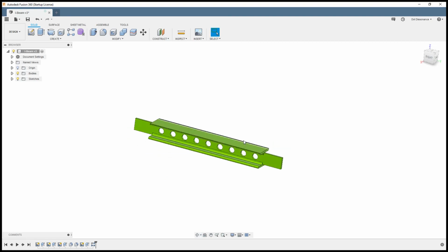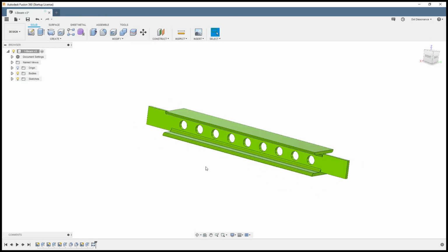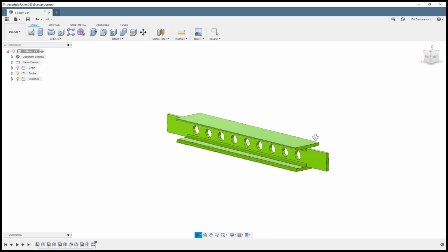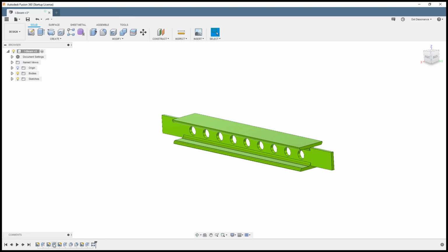Now, in this particular model, thinking ahead, and this is a really good design theory tip, I guess, is talk with all your people and decide what the future of this model is going to be. And I say this tons and tons. As an example, the flange on the top and the bottom here, they're both the same, as you maybe would believe that they always would be. For most people, that's the way you've seen I-beams, but they could be different. So purposefully, I made this as two separate sketches and extrusions, just in case. Okay, so we're going to mess with that in a second.